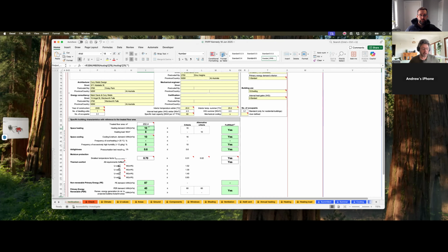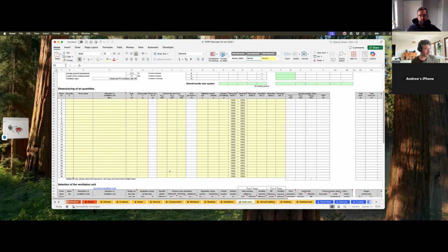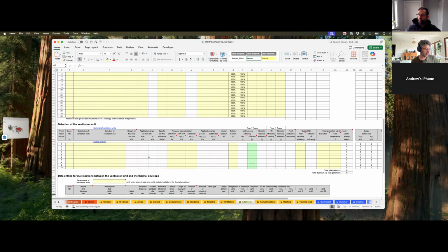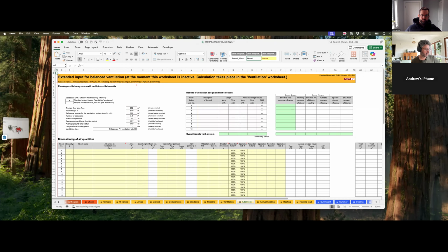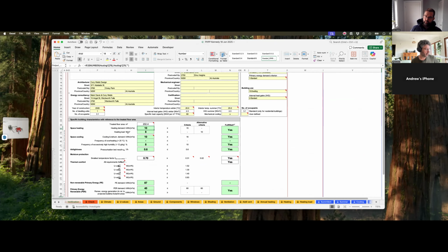So I've got a project under construction in Blackheath where there were some big gum trees blocking off winter sun. So we were right on the edge in terms of our heating demand. If I had a ducted range, it would have put us over. So we've had to go for recirculating there and a performance solution. But that's not ideal. Once I know the unit you're going to use, I'll put all that in here. I probably could have put a temporary unit in, but we've got plenty of room to move there, so it's not an issue.